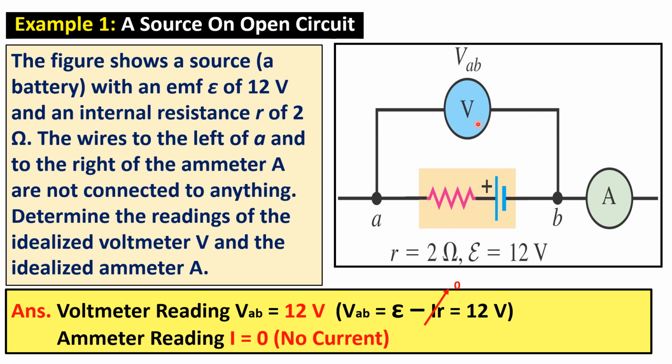If a voltmeter is so designed to have an infinite amount of resistance, an ammeter, on the other hand, is designed to have an almost zero resistance. That is why an ammeter must be connected in series with the point where you would like to measure the current, because whatever current passes through, for example, point B, will also be the current passing through that ammeter.